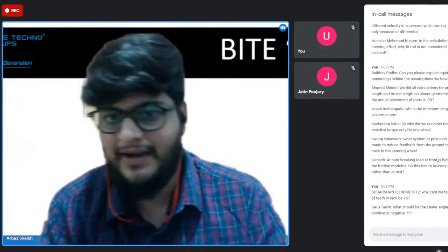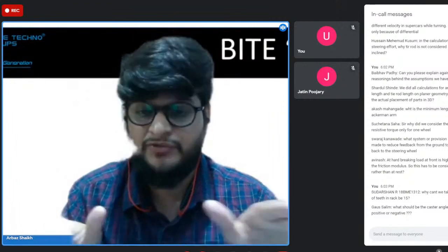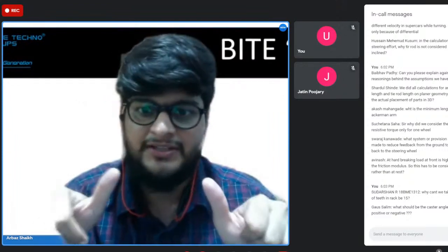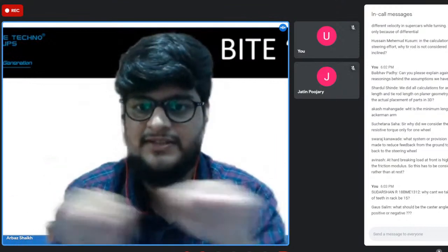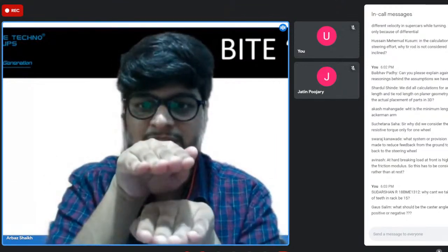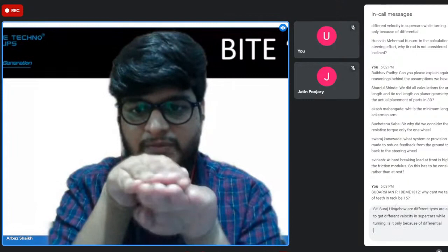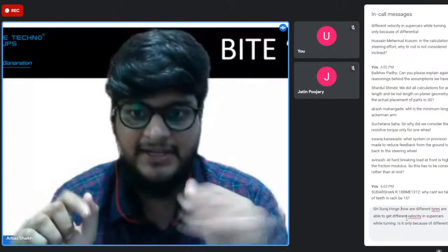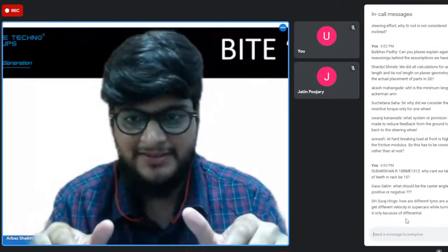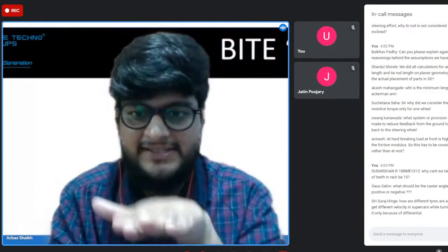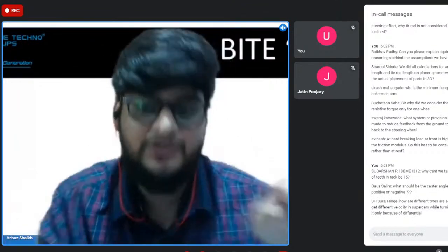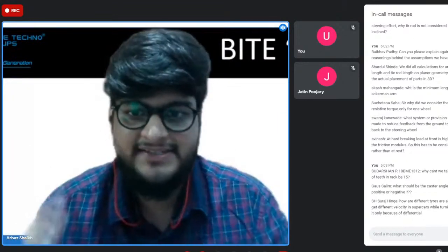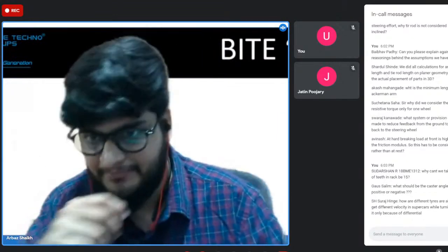So imagine the Ackerman arms, both of the Ackerman arms will be in the same plane. Your rack will always be on a plane parallel to your Ackerman arm. So if this is the plane of your Ackerman arm, this will be the plane of your rack, and these two will be parallel to each other, right? And the only change that you need to make is the tie rod length. So simply, you will place these two on different planes in software, and you can calculate the length of the tie rod easily. Everything else remains the same, only the tie rod length changes in that case.